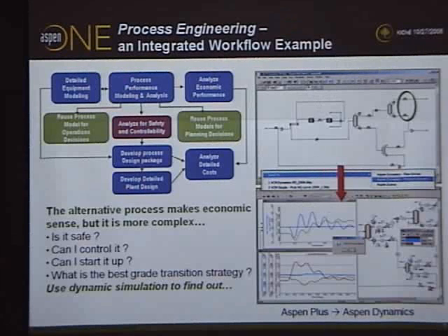Now, we've determined that the new design saves energy, that it's economically attractive. That doesn't mean that we should go ahead and build it in the plant. Maybe the new design is not safe. Maybe the new design is hard to control, hard to start up. So to understand the overall impact of that proposed change, we really need to consider the process dynamics as well as the steady state performance. So the current practice today in industry is to use dynamic simulator to really study the way the process behaves.